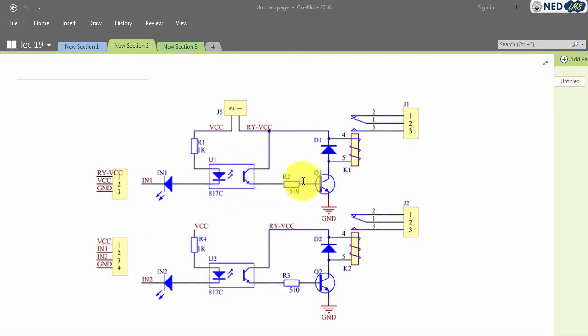That will turn off this transistor, and that will turn off this transistor, and it will turn off the coil over here. I mean, this coil will no longer have the path to the ground, and the circuit is actually broken. So this coil will de-energize using this diode, because it's collapsing the magnetic field. The voltage polarity will reverse, and this diode will become forward biased, and all the energy of this coil will circulate in this small circuit and dissipate, and the contact 1 to 3 that was made before will now return to its original position, and common pin 1 will be connected to 2.